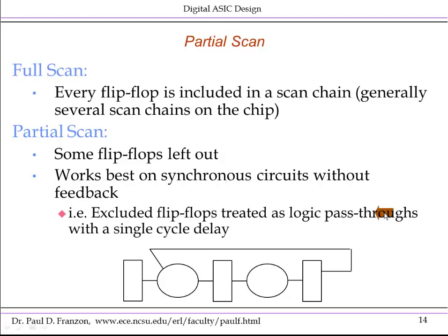Basically, if you have a circuit, such as on the bottom here, where this intermediate register simply passes through the logic values there to the logic values there on the pulse edge clock without feedback around it, then you don't have to scan this. What you have to do is, for purposes of working out your test vectors, ignore this because it just passes through the results. Apply test vector there, 2 clock cycles later, get a test result there and scan that out.